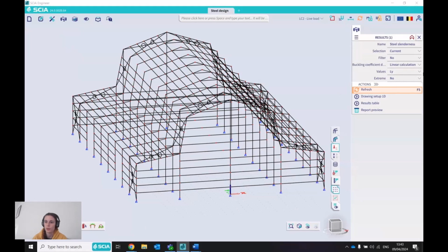It's possible also to display them. Let me print here the KY values. I need to have a selection. Let me select this one. Okay, yeah, so here you see already we get to some buckling factor of 10, which is probably too high for this type of column.